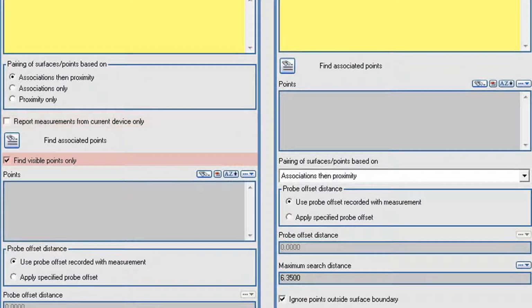The default setting for points that will be loaded automatically when the user clicks on Find Associated Points or Load All Objects from Active Filter with the All Points filter will now be from the current view only, and points that are in a different view may be loaded by selecting them from the Object Manager. It should also be noted that the default setting for the analysis will now be performed with no regard to the current device. Any points that are selected will be analyzed without checking which device they are related to.